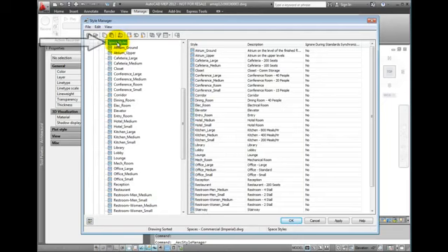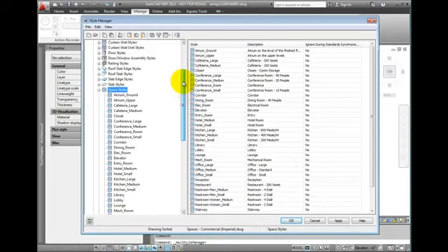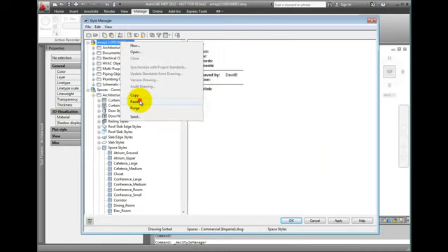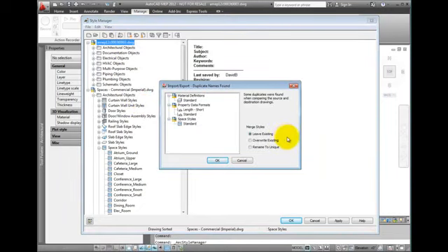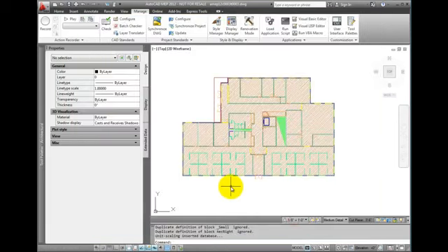To copy all of the styles into our drawing, right-click on the Space Styles title. You can also use Control to pick several styles in the right side of the dialog. After selecting, select Copy. Scroll up to the exercise file. Right-click on the title and choose Paste. When the Import-Export Duplicate dialog appears, make sure to leave Existing checked. Then pick OK. Pick OK to close the Style Manager.